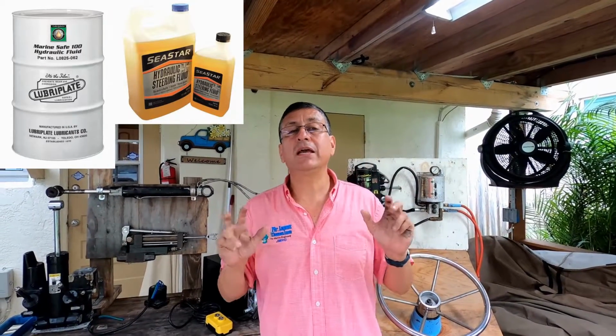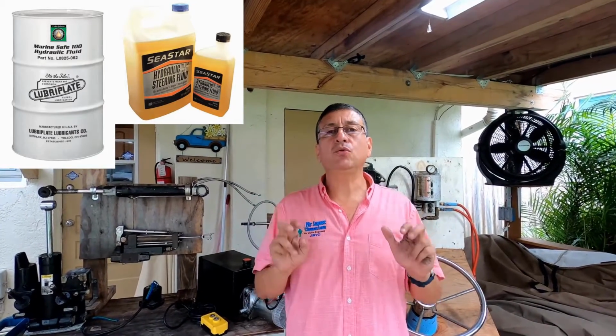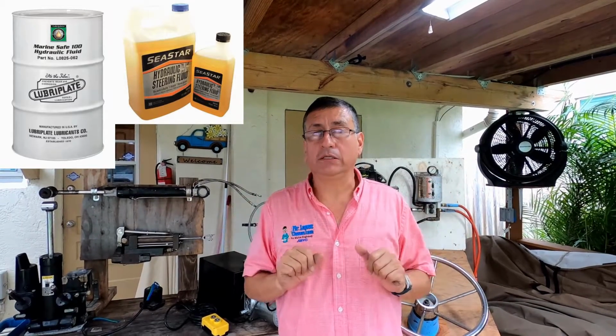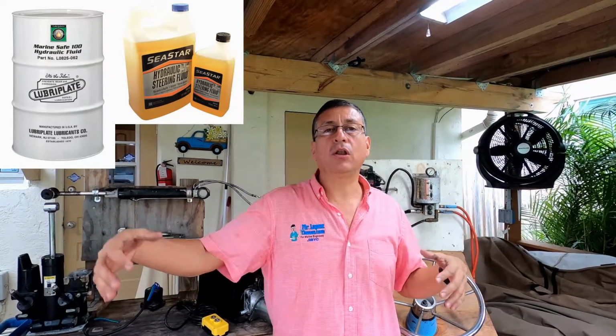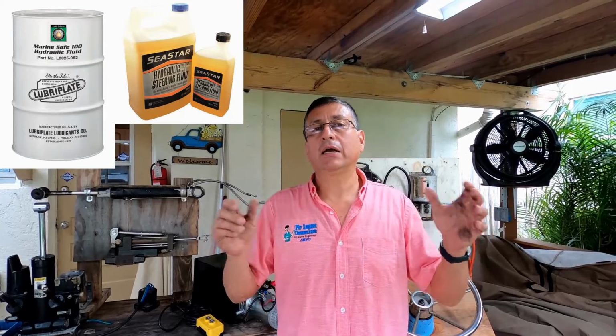Never try to use generic oils. Never try to use cleaned oils. Those are oils that people collect from garages, add additives in order to clean them, and after that resell again. No, I recommend using original oils recommended by the manufacturer. This is important. The life of the hydraulic systems depends on the quality of the oil.